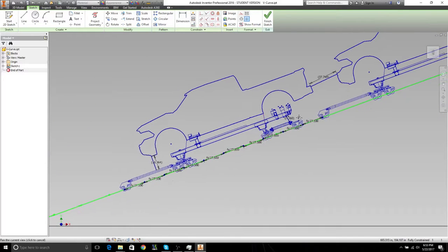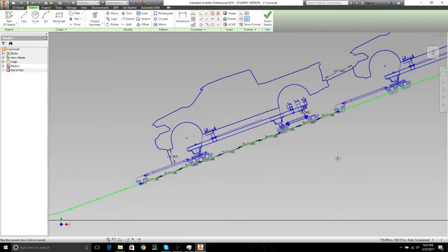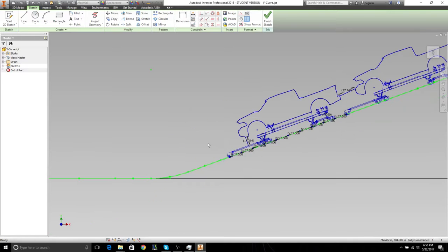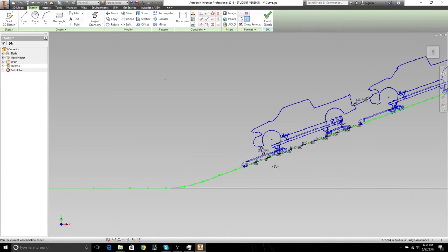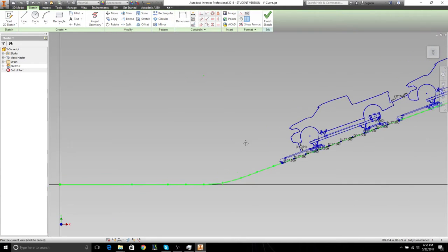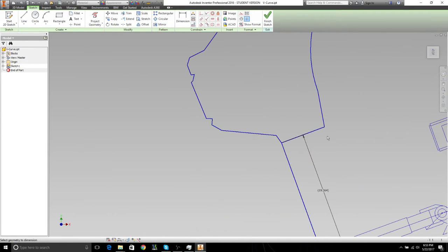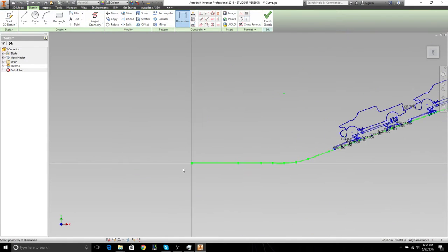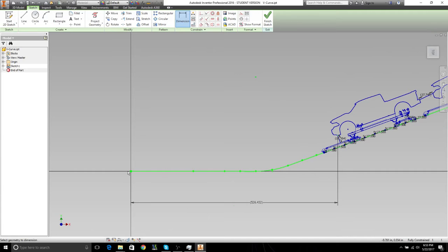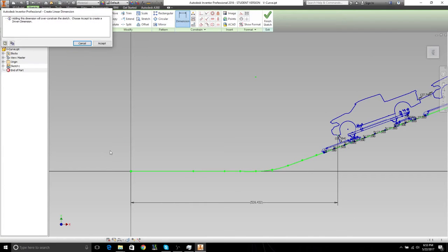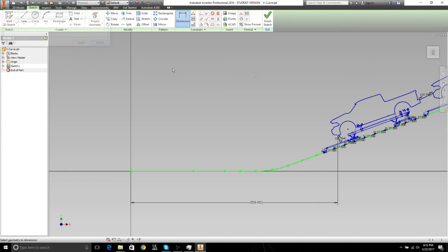And let's say also we want to track the path of a specific point of interest as it moves throughout the entire curve. We can also do that, but that point has to be referenced from the origin here. So say I want this point here, it has to reference from the origin, goes there for the x dimension, and goes there for the y dimension.